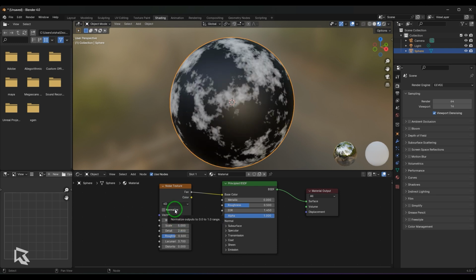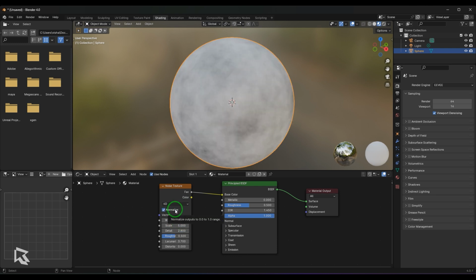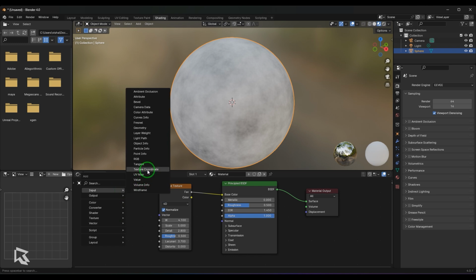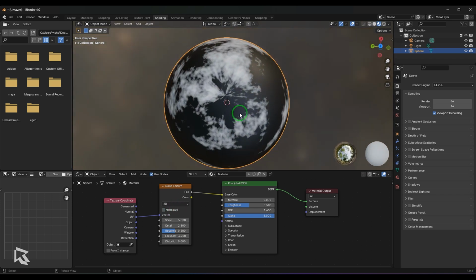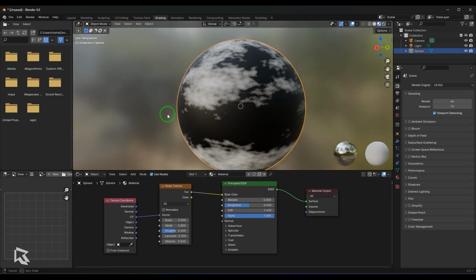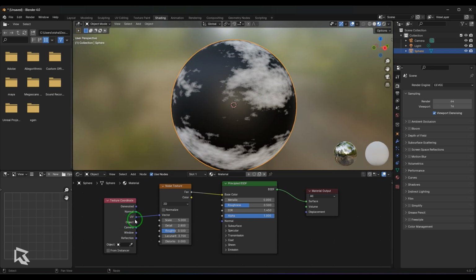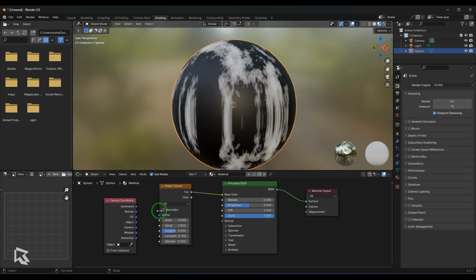And as I told, vector normalizes the value between 0 to 1 region. And then we got vector input, where you could able to connect one procedural texture, I mean any texture coordinate to that. Like I can just connect the UV, and then you should be able to see that 2D texture respects the UV space. You got the poles here, and it's laying the texture on the UVs of the model because I've connected that way. So you can explore more on that side, but this is what we have for the noise texture.